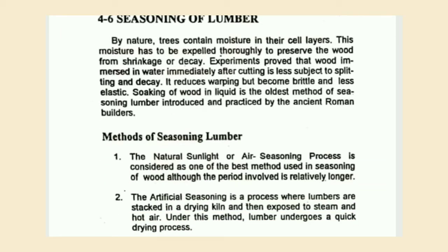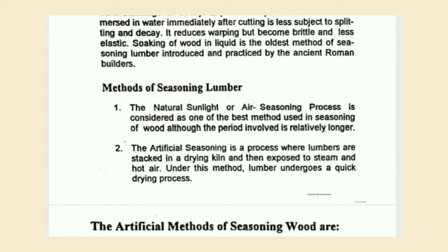By nature, trees contain moisture, so lumber can be seasoned. The moisture contained in lumber must be expelled thoroughly to preserve the wood from shrinkage or decay. Experiments prove that wood immersed in water immediately after cutting is less subjected to splitting and decay. It reduces warping but becomes brittle and less elastic. The soaking of wood in liquid is the oldest method of seasoning lumber, introduced and practiced by ancient Roman builders.